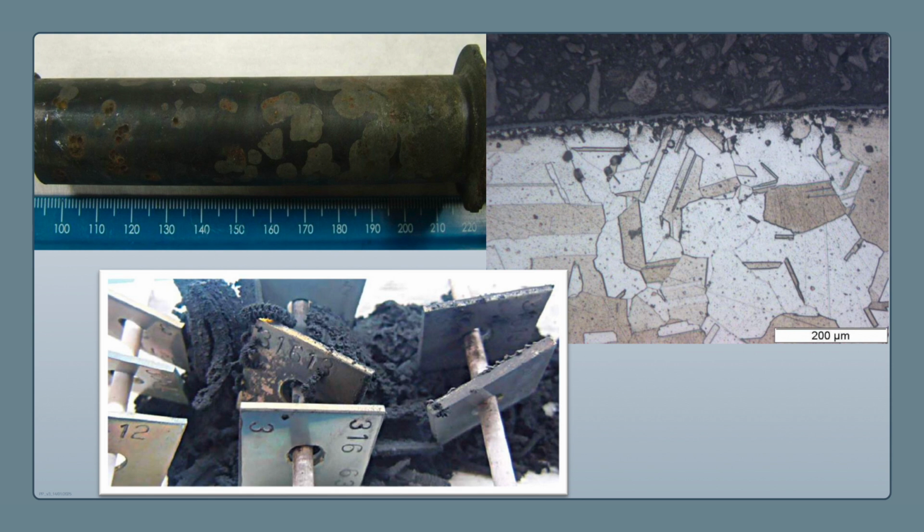You've actually shared a photograph with me, which I think might be quite helpful. So if we have a look here, here's obviously the steel tube, and you can make out in the photograph these pits. Is that where this form of corrosion has occurred? Yes, this whole sample was from that section, but this nicely shows us the dusting effect. When they remove the sample from the plant, the dust falls off because it's very brittle and quite loosely adherent. So through the investigation, you really have to look at the operating conditions to try and identify the type of corrosion. And with metal dusting, it's extreme oxidation.